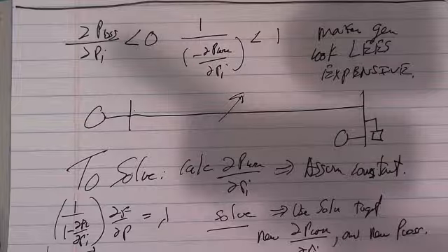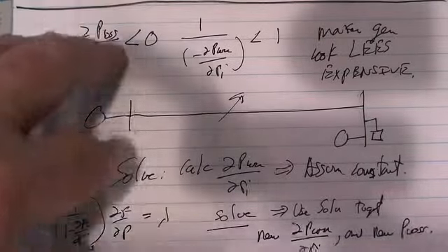Later on, we'll give you a piece of code that will take a power system and do an economic dispatch. Then it'll do a power flow, calculate the power flow, and then from the power flow, calculate the losses and the incremental losses, and then come back and do another economic dispatch. So before we leave this topic, we'll just point that out.